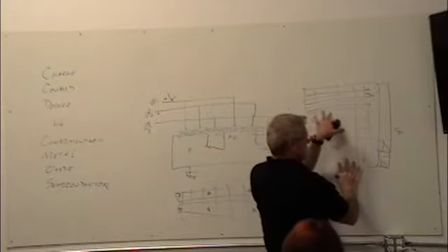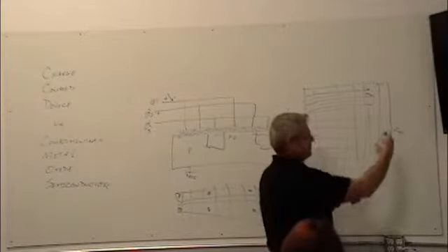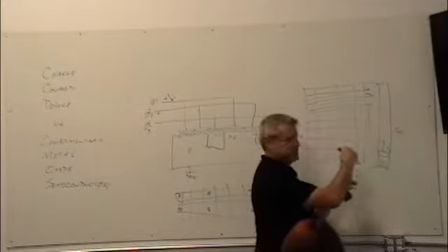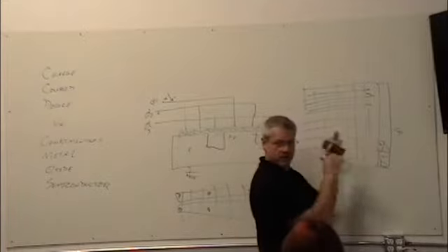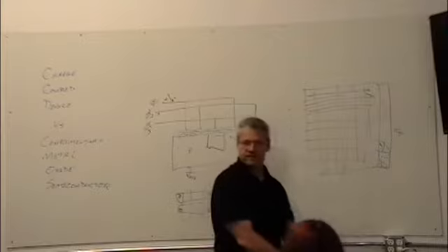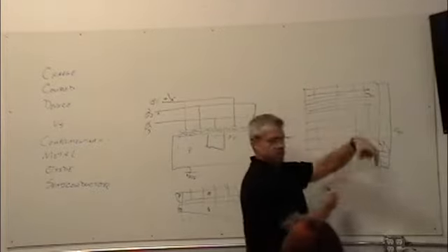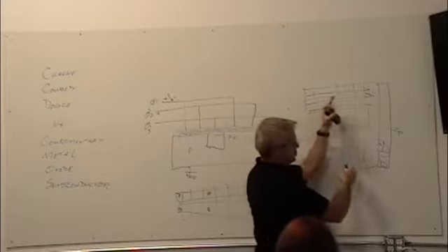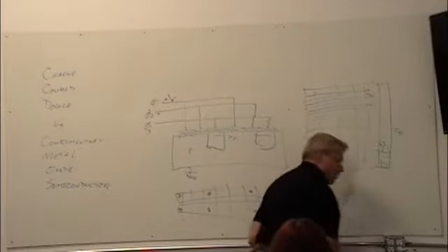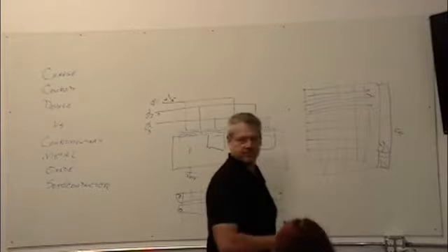So everything will go step, step, step, and they'll land here, and they'll time these phases the same way, so that this one here is open when it lands, and then they'll go step, step, step, step, and you'll step all these out the end. So you'll take one column, or one row, depending on how they've done it. You'll shift it one column, and then you'll read out that whole column. And then you'll shift it another column, and then you'll read out that whole column.